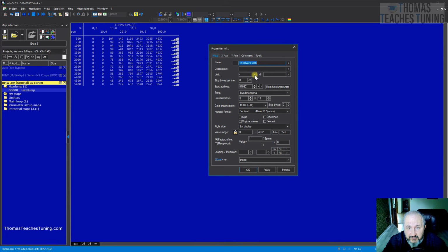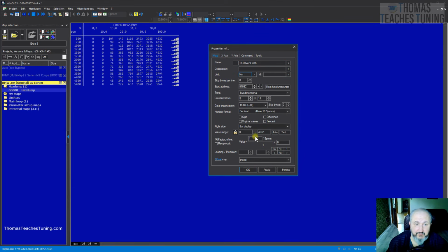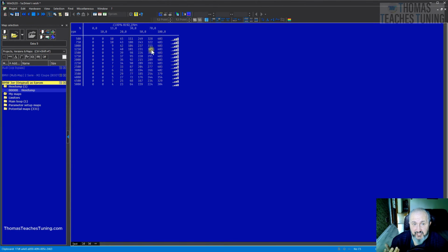So therefore, we enter .1, and that completes the conversion. So what does that mean? If the driver presses the accelerator, for example, to 50%, and the vehicle has an engine speed of 2000 rpm, then the car will implement 215 Newton meters of torque.